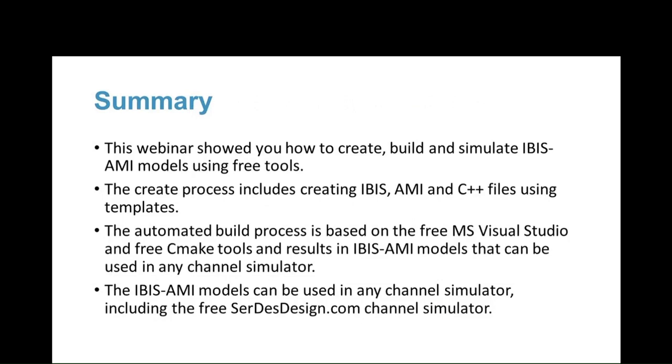So this webinar showed you how to create, build, and simulate IBIS-AMI models using free tools. The create process includes creating IBIS-AMI and C++ files using templates. The automated build process is based on the free Microsoft Visual Studio tool and the free CMake tools, and results in IBIS-AMI models that can be used in any channel simulator, including the free SerDesDesign.com channel simulator.